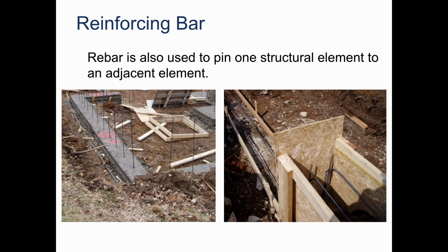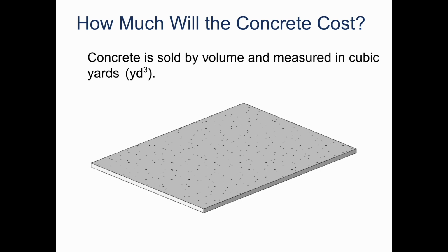Also right over here, we can see that there is this upper part here, and then it kind of moves down, and then it goes down to this bottom section here, also to end up pinning those elements to each other as well. You can also see that there's that overlap with the rebar too here, and then they have little wires in there connecting the two to make sure that it stays in place as we pour the concrete in.